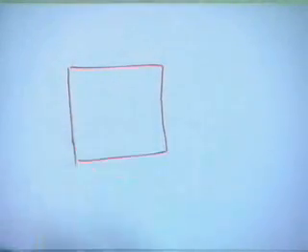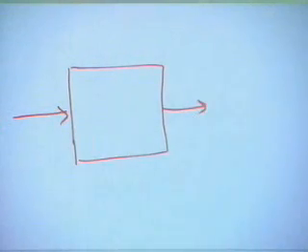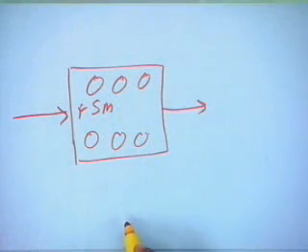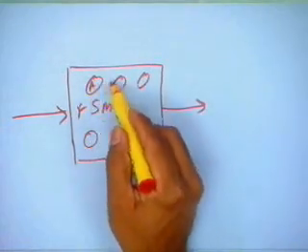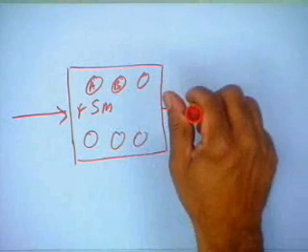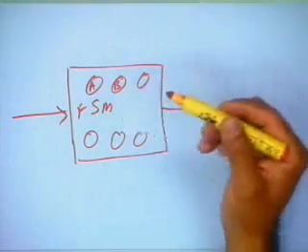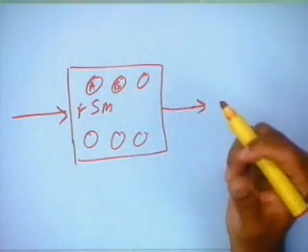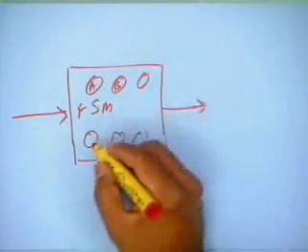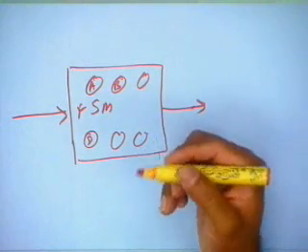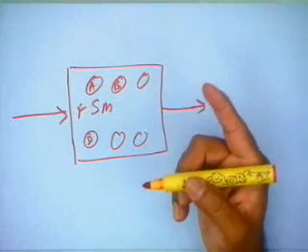What it implies is, if you look at the black box, this is my state machine. I am allowed to apply some input and I am allowed to monitor some output. The machine could be in any one of the states that I have: A, B, C, any state. So, I apply this input sequence and I am only allowed to monitor the output. By looking at the output, let us say the output pattern is a certain pattern, I can be certain that if I receive this particular output pattern, the machine has reached state D, for example. I do not have to be sure about the starting state, I only have to be sure about the final state.